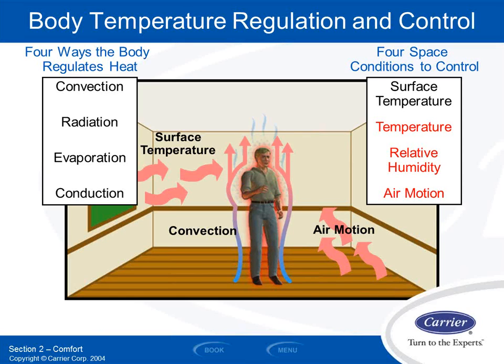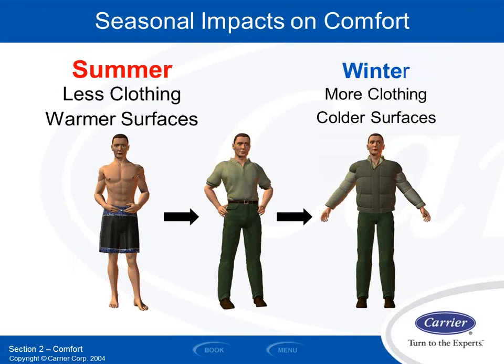The surface temperature is a little harder to control. For the most part, I'm controlling the temperature of your desk surface by controlling the air temperature, which is indirect. In some cases, though, I can do a really good job of controlling surface temperature, and typically that's with radiant floor systems, where I bury PEX tubing in the floor itself and run warm water through that, or cool water, to temper that floor surface to make you more comfortable in that regard. So we can do some stuff with that, but that's not the main one typically.